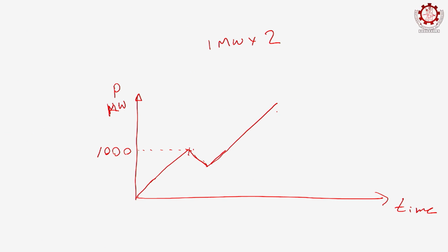And if there is still more water, we will take the first machine also to full load. If there is still more, let us assume this is 800, so this may be 1800, and then you take the first machine to another 200 to make it 2000. So, likewise in operation, depending upon the type of turbines you have, you have to optimize how to load and unload them.